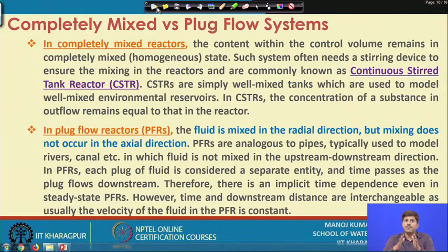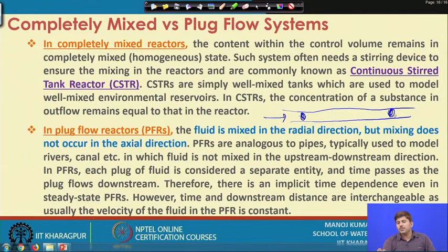Whereas, the other type of flow regime is the plug flow reactor, where fluid is mixed in the radial direction only and it does not get mixed in the axial direction. So, these PFR or plug flow reactors are analogous to, let us say, a pipe. So, in a pipe if you are having a flow, okay, the water here does not get mixed with the water here, okay. Water here will flow and will reach this place after a certain time, but it is not going to mix with this plug or this packet of the water.